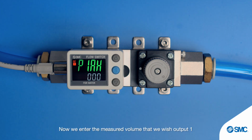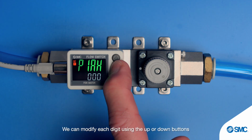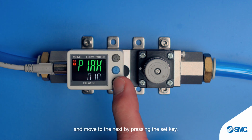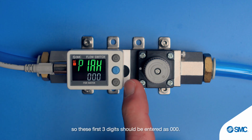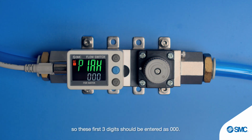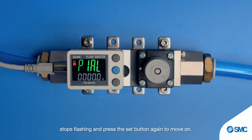Now we enter the measured volume that we wish output 1 to activate at, the threshold. The first screen allows us to confirm the first 3 digits of this value. We can modify each digit using the up or down buttons and move to the next by pressing the set key. In this example, we want a small accumulated volume, so these first 3 digits should be entered as 000. To accept the values for the first 3 digits, hold the set button for more than 1 second so that the digit stops flashing and press the set button again to move on.